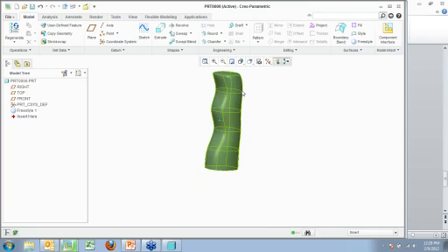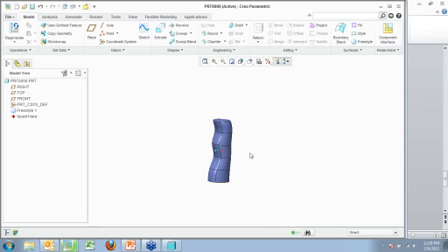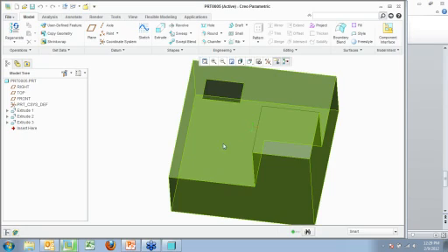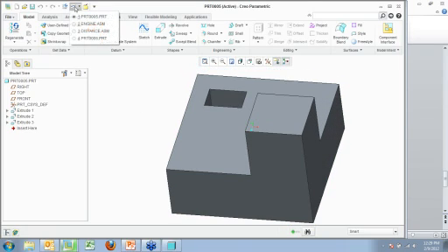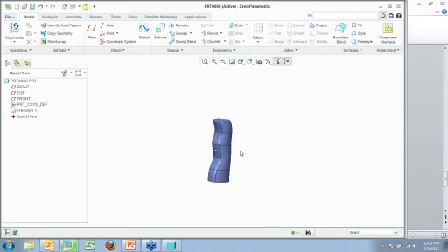This is a surface. That's another thing that they do in Creo Parametric, is they also take surfaces and turn them kind of this purplish color, kind of a light blue violet. Solids, as you can see from the other part I made over here, are gray. So you can tell from looking at something if this is a surface or a solid. Well, let's say I want to go in and cut a hole in this for the actual tennis handle to go in. I can select it, solidify.